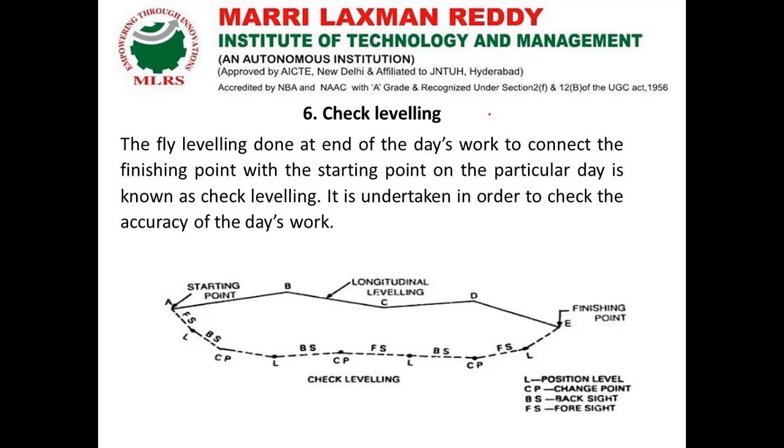This can be done for the day-to-day work. If I do the work for this day and have covered some 2 kilometers, I have to check whether that 2 kilometer work is correct or not with the help of the end point to the benchmark reading.